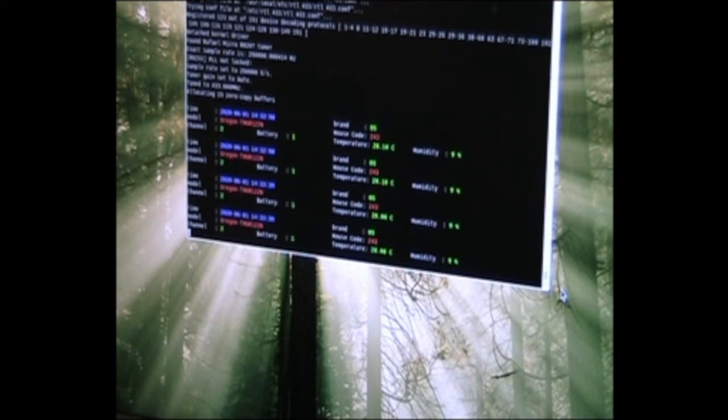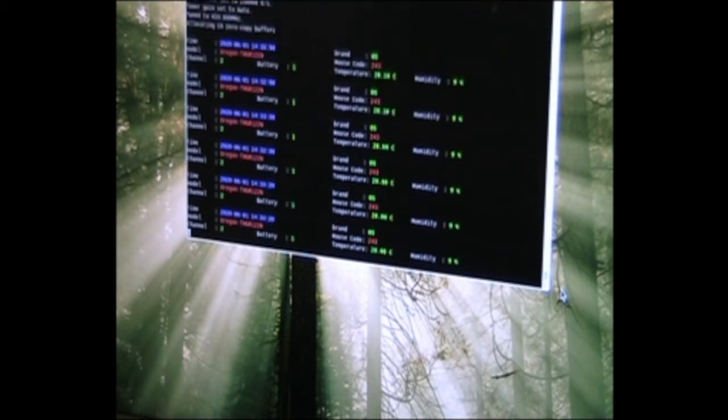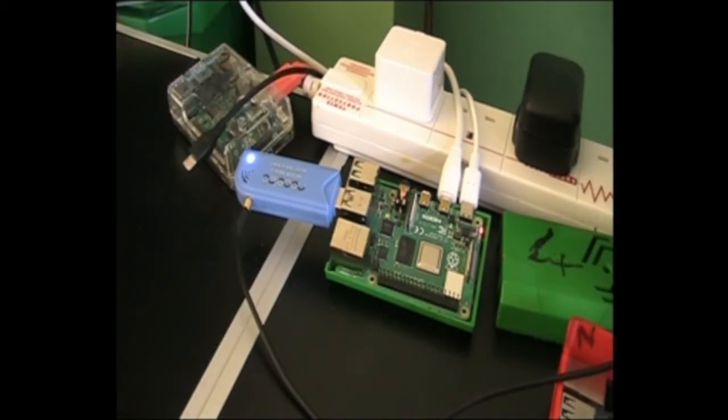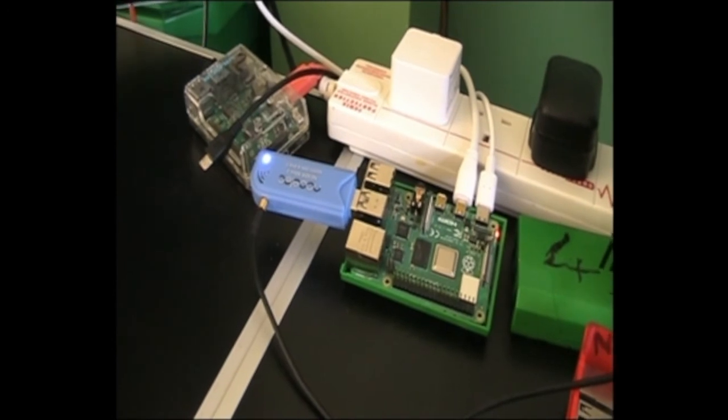Not very clear on this particular, but all these single lines of data. Each new line of data is the ones with the blue date time groups on it. And as each one comes in, you see the latest pulse of data coming from that small 433 megahertz transmitter. So here is the SDR plugged into the Raspberry Pi. The signals coming from the small sensor is interpreted by the radio and then is decoded and displayed on the website, or on the screen, sorry, through the Raspberry Pi.